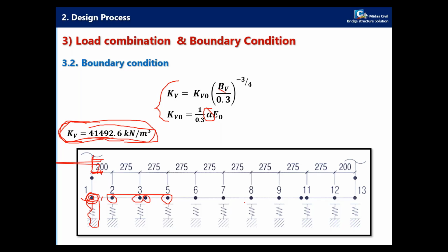I know that a lot of people there studied finite element analysis. So you need to specify a proper distance of the springs in order to have a good simulation result. If someone spaces the springs widely like this, the result can't be the same as someone who places a lot of springs on this side of the structure.